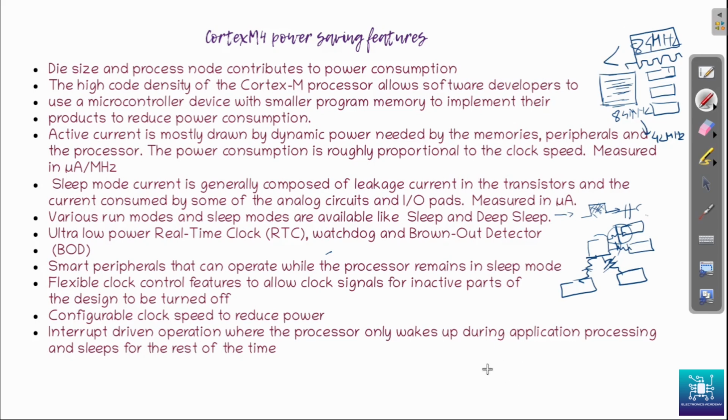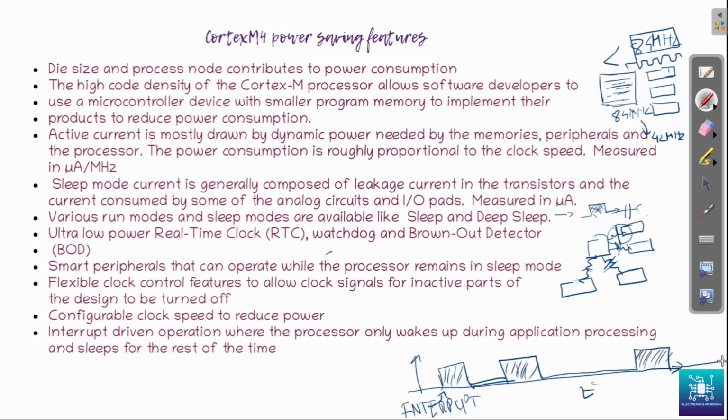So there is a design paradigm where, say, this is the time axis, and the processor will only wake up, do its job, and then go to sleep. This wake up is always triggered by an interrupt. So there's an external interrupt or any interrupt that comes in. It does its job. The moment it finishes its job, it again goes to the sleep mode. Then again some interrupt will come at some point. Again it will go into the sleep mode, and this interrupt may be periodic or non-periodic. Sometimes the interrupts may come in periodically, sometimes non-periodically.